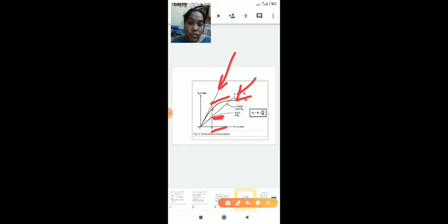Here this is a tangent line, it touches the open circuit characteristics here. At open circuit characteristics, this machine rotates at some full speed of N1 rpm. Next, if the critical resistance touches this, at this the speed is changed. Nc is equal to N1. Critical speed is equal to N1, the full speed, into RT by RS. This is the R. By this we are getting the critical speed.